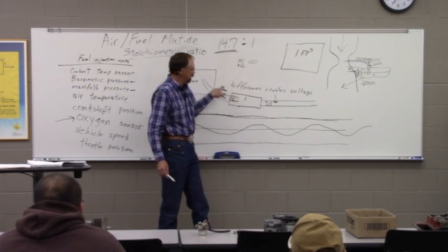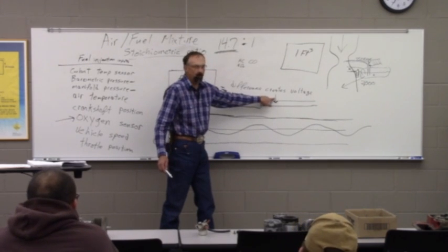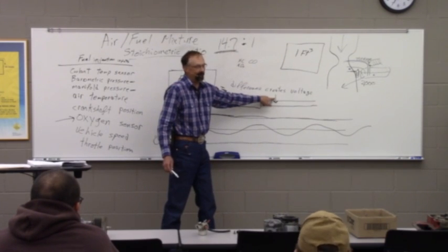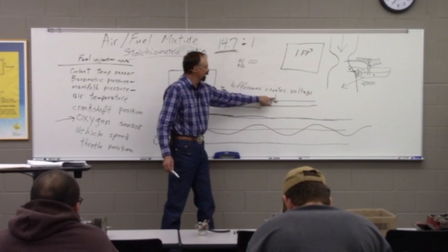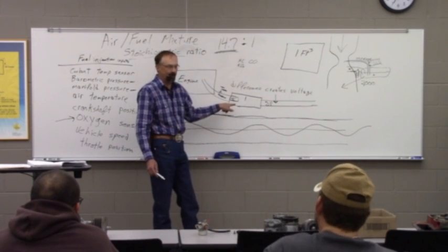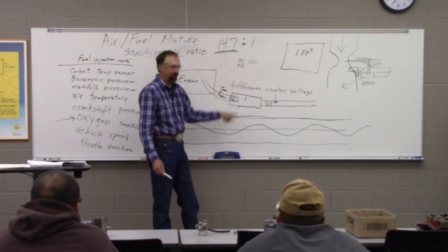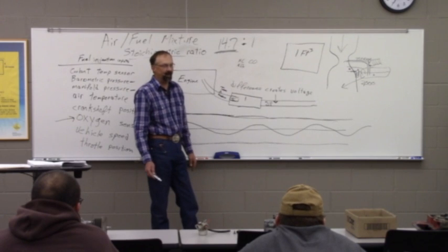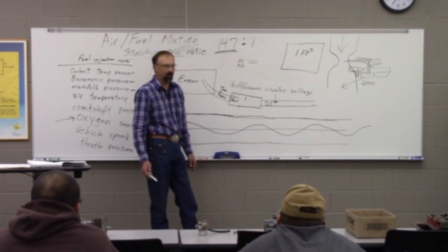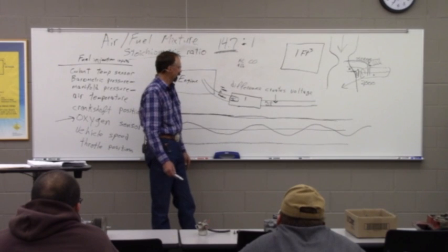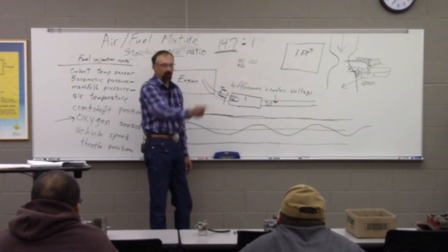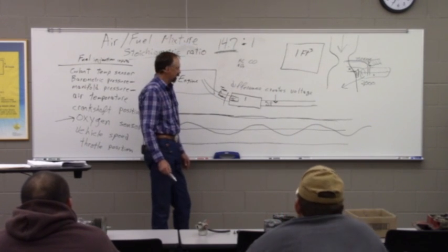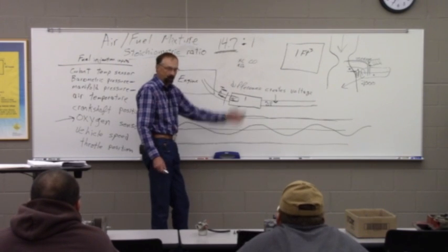So when it codes for downstream O2 efficiency, what it's really saying is, hey guys, we know the catalytic converter ain't doing nothing, and it's dead, and if you want this light off on your dash, you're going to have to replace the catalytic converter. In the 80s, those catalytic converters plugged up really bad, and they were pretty restrictive, and a lot of us would saw them out of our pickup, and no ill effects, other than we were emitting more pollutants than we should.